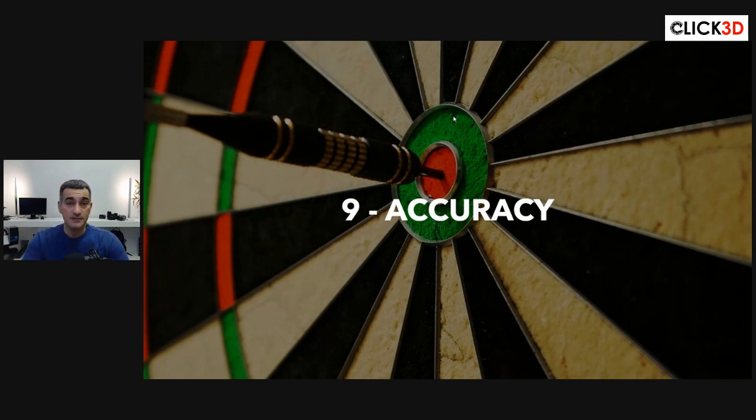Now, there have been some studies that compared a similar sized object, let's say like a parking lot, to the laser scanner. In fact, I did a study a while back where I took a parking lot and used a total station to mark a bunch of points. Then we flew a drone and created a 3D model, and then we laser scanned it and made comparisons.